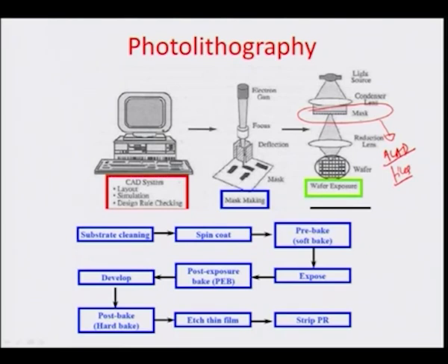And then there is a light source at the top here. The light falls onto the mask and passes through it, and whatever features on this mask are made for blocking the light would block those portions of the light, and whatever features are open, light passes through them and falls onto the wafer, which is coated with the resist. So, the wafer is coated with the photoresist, and thereby it creates the imprints onto the top of the wafer, which you can develop later to formulate the features.